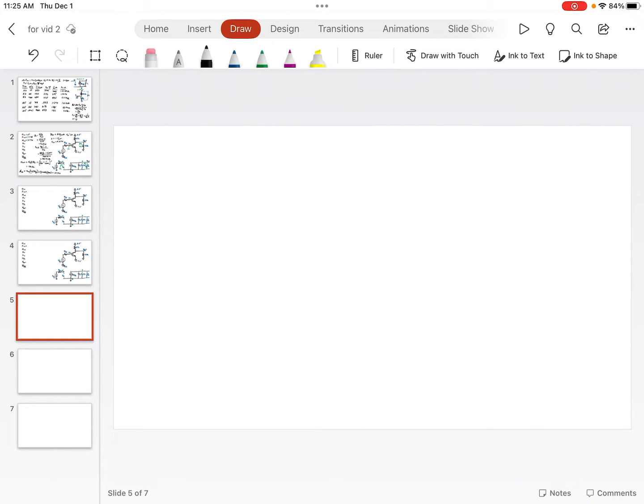AV is exactly the same thing, except that it includes the load resistance. So AV naught was the open circuit voltage gain. AV will be the voltage gain including the load, but not including the signal generator.